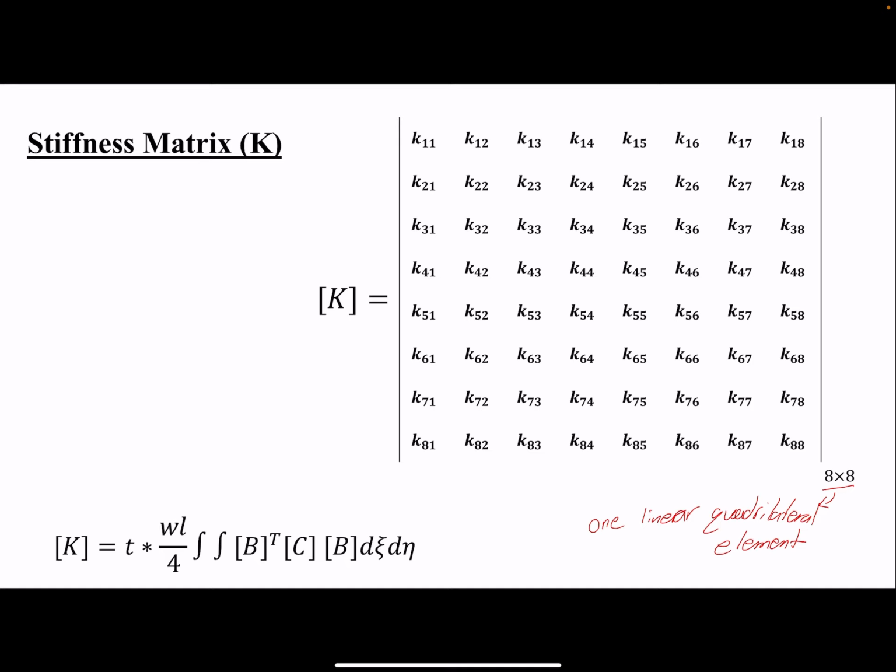We find a local stiffness matrix for each element, then we put them together to find the global stiffness matrix. We apply the boundary conditions, we find the nodal displacements based on that, the stresses, the strains, and so forth. So our task was to find the stiffness matrix, which we did. The rest would be the same as any other FEA procedure.